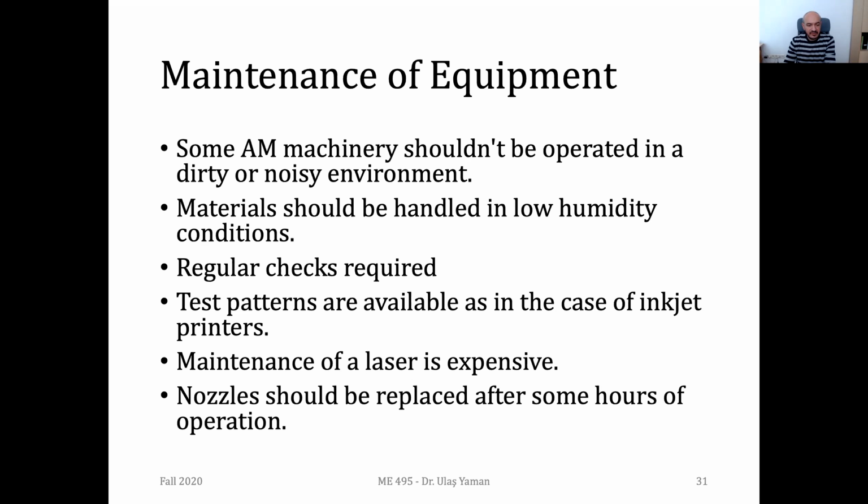Another issue about the head of the printers is the nozzles. If you are using fused filament fabrication type of systems, from time to time you may need to change your nozzle since it may be clogged, and you may have some particles at the tip of your nozzle, and you may not be able to extrude material.